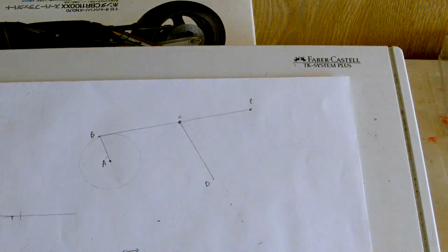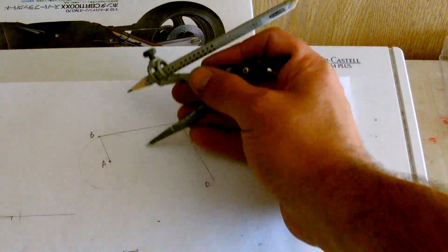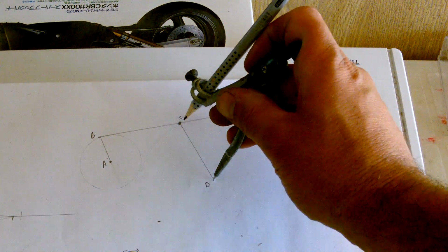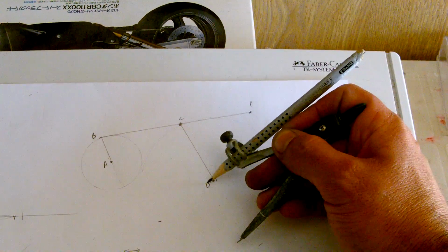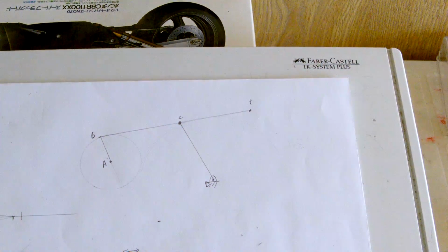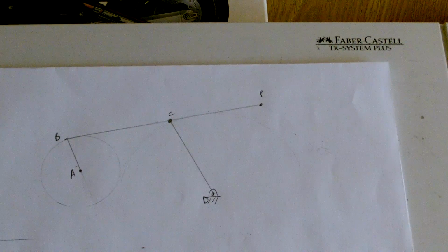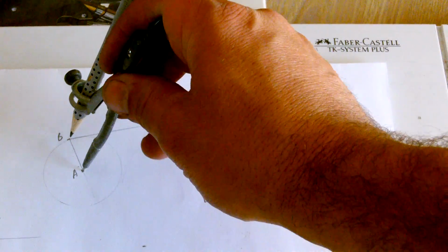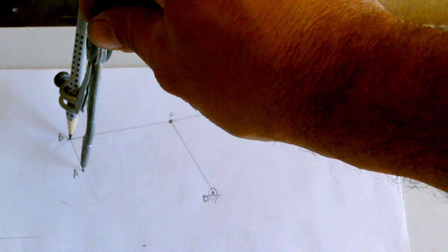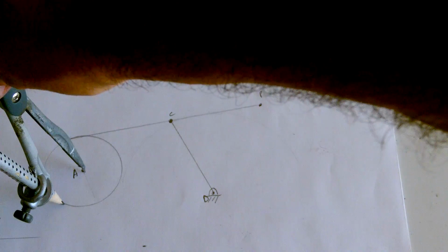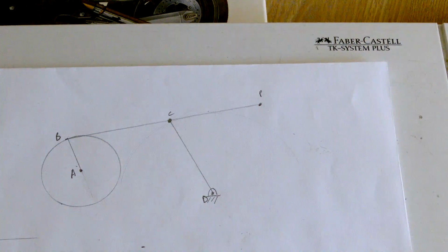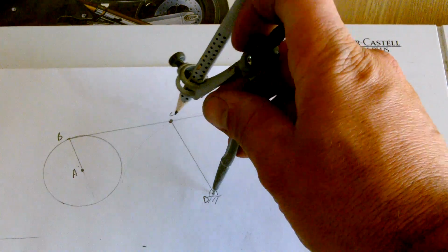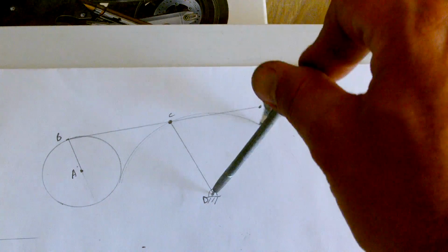So what I need to do is, as I've already done here, I've drawn a circle around A, and the locus of C, since D is fixed, usually the symbol for fixed is something like that. I want distances. I don't want angles, I want distances. So AB is always that distance. It causes that locus for B. DC is always that distance. Now since D is fixed, C can only move in this arc.